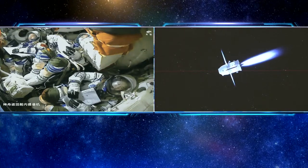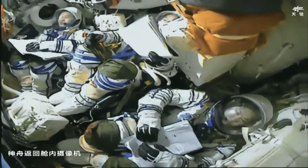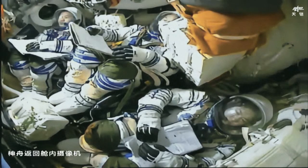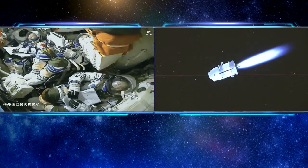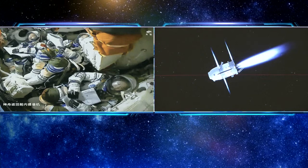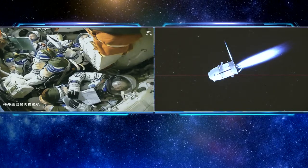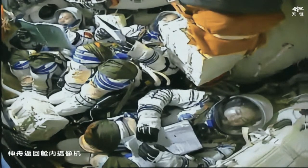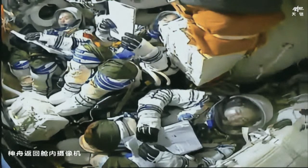So, as I understand, they finished at least 3 key steps on their way home, right, Professor Yang? Yes, exactly. From the previous video, we can see that although it is a 3D animation, it represents the real-time status of the spaceship. At this moment, we are conducting the de-orbit burn, which means we will decelerate by shedding a remarkable amount of energy, so that the trajectory of the Shenzhou spaceship turns from a circum-Earth orbit to a trajectory which can dive into the atmosphere. With this very important measure, we can return to the Earth with the help of aerodynamic forces, which reduce the speed of the Shenzhou spaceship, and then we can deploy the parachute and come back to the Earth.